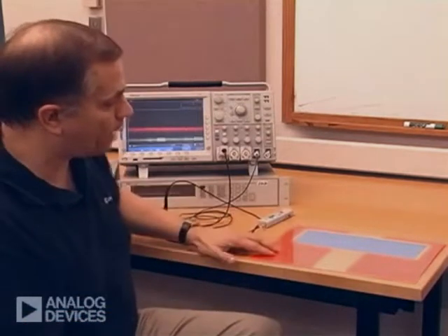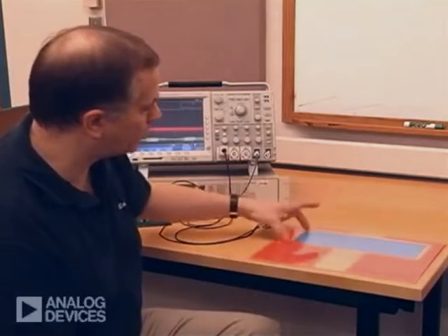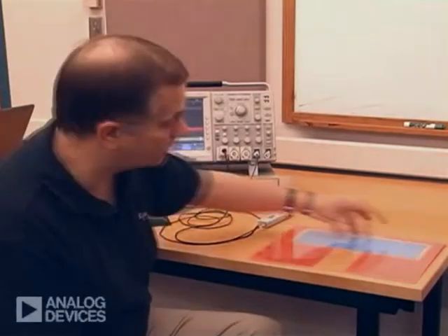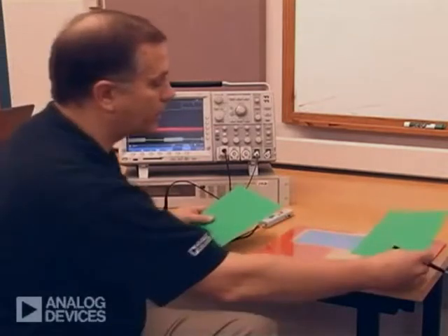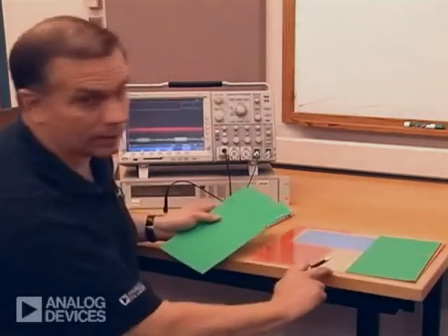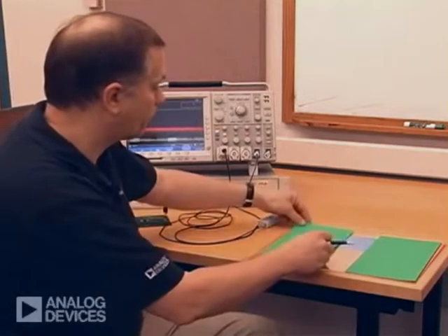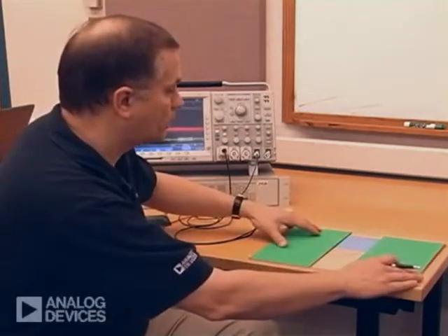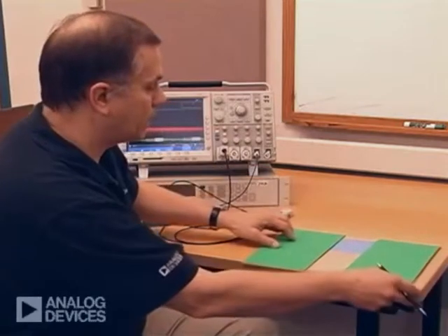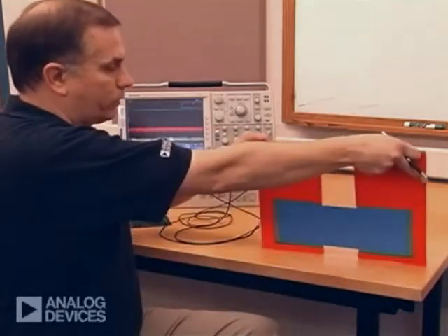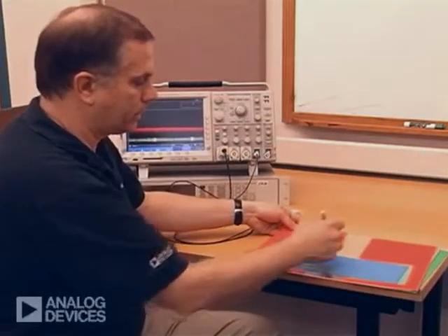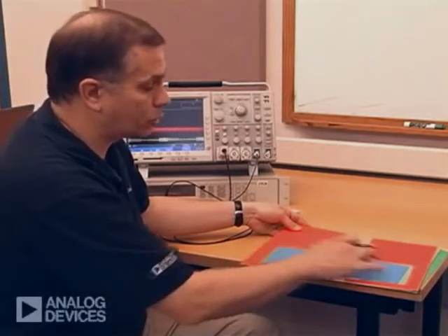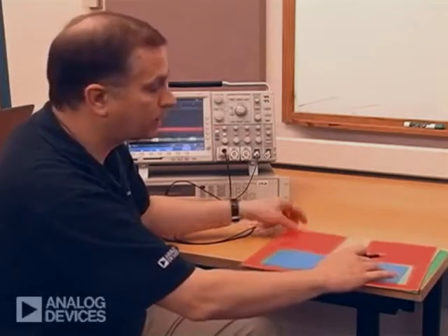So if we have a power plane and a power plane, and we build an isolated floating structure in that same plane, if we then lay the ground plane on top of that through a very thin layer of circuit board, as before, if we flip it over, you can see that we wind up with areas of overlap here and here, which creates, again, very good capacitors with an extremely low inductance path between them.